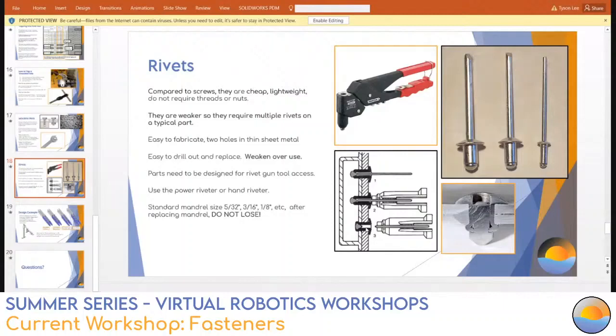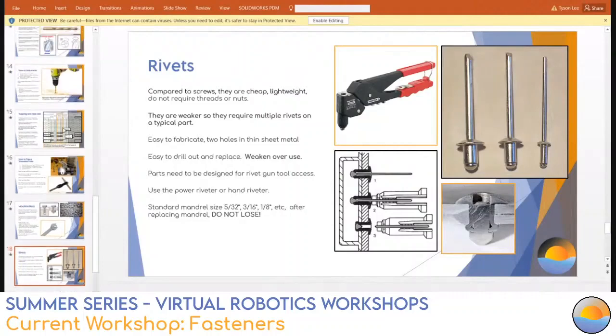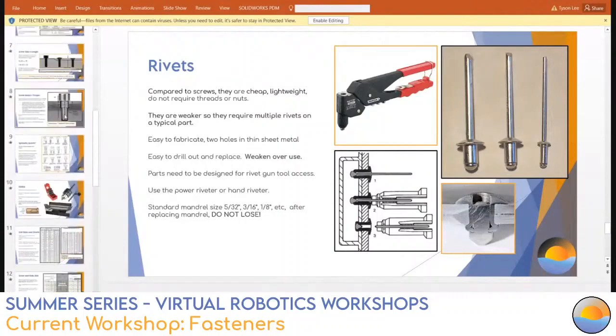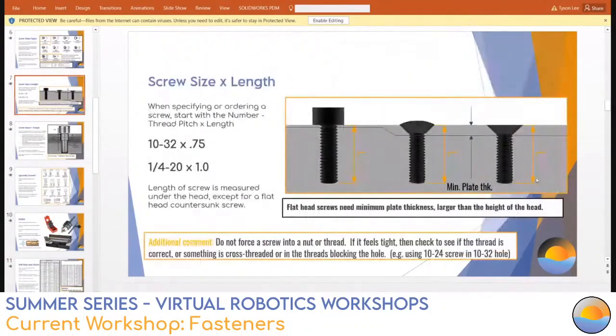You have to consider the extra space or gap that gets created, or countersinking, or the special rivet nuts that are countersunk. But then again, like I mentioned about countersunk screws, you have to consider the thickness of the plate. At that point, I'm not sure what you're gaining by how thin of a plate you're using.